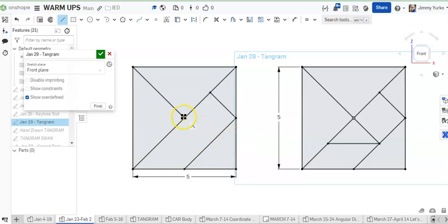We're going to go ahead and extend this line perpendicular to the diagonal here from the origin and to the midpoint of that diagonal line right there. And remember to click on the endpoint, two clicks on an endpoint to end the line. Go ahead and draw across here, and there you have it. Use the escape key to escape the line.